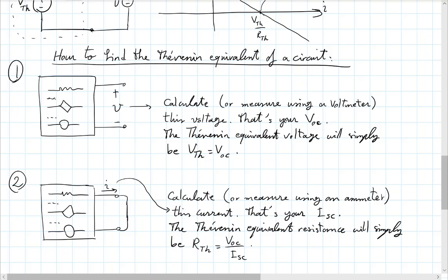So what I said here should not be treated as a rule set in stone, but as a guideline maybe, because perhaps it is easier. This is a relatively easy point to calculate. You just calculate the voltage between 2 points. And here you just added a wire rather than adding another voltage source. But it was not absolutely necessary. So this is the Thevenin equivalent of a circuit.